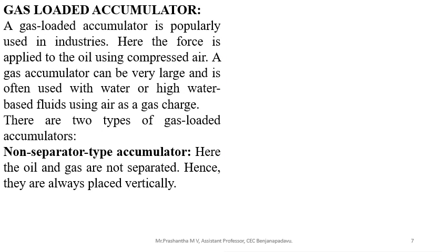Third type accumulator, that is the gas loaded accumulator. As the name implies, here the fluid energy, the pressure energy, is stored against the gas load. These are also called hydropneumatic accumulators because gas is used. The compressibility of gases accounts for the storage of potential energy.